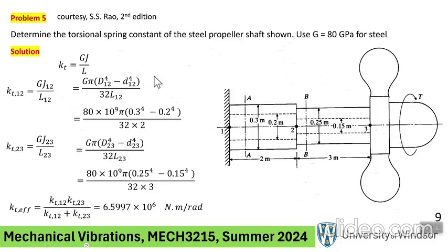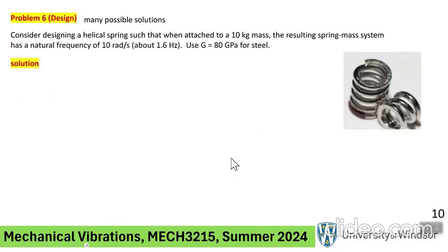So it was a slip of... if this guy was in the middle and the right side was fixed, then these two torsional springs act in unison, and they will be parallel. Just add them up. But here, of course, you can see that because they're in series, the stiffness is smaller than them individually. If you get this number, it's less than that, and it's less than this. All right. Let's do this problem.